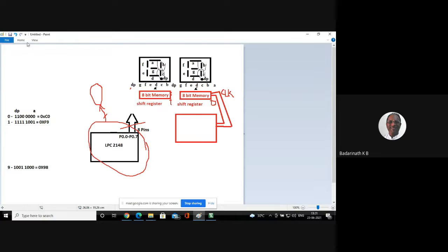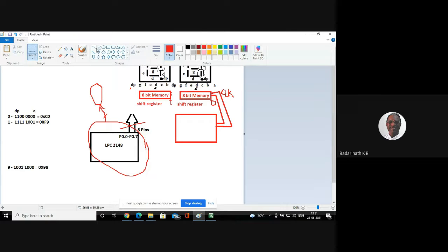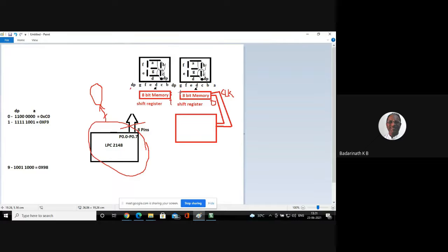now what I will do is select the last data from the microcontroller's shift register and give it to the input of the second shift register. So the first data, which is coming from the microcontroller, is given to the input of the first shift register. After you give 8 clock pulses, one data is ready here. Now I'll cascade this shift register to another shift register. The output of the first shift register I've connected to the D input of the second one.